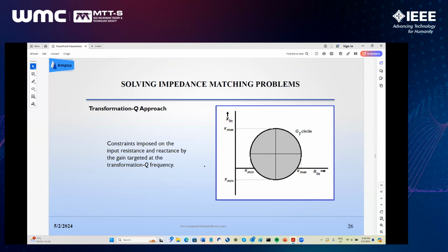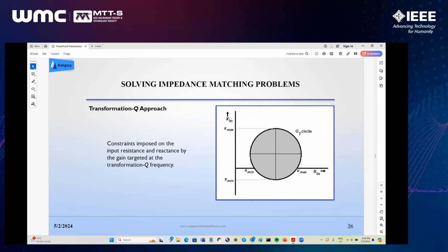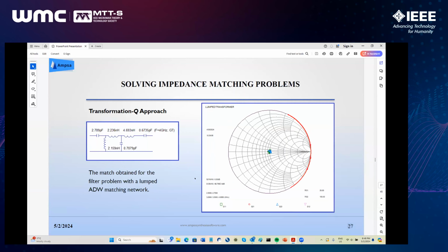So the last two Qs, so Q3 and Q4, they're not independent, they link to the gain. So this makes it quicker too. So apart from the fact that the Qs are limited in range, I then also have the gain to help me because the Qs cannot go too wild. The gain puts a further constraint on them. So one can do a realistic search on the Qs for up to 6 elements unconstrained, fairly efficiently.